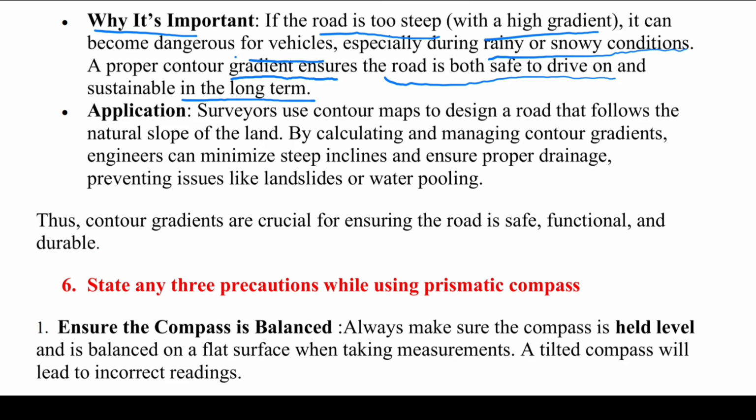And the application: if you are a surveyor constructing the contour map for roads, following the nature of the slope of the land, we need to know the slope of the land and how the terrain is. Based on that we have to fix the contour gradients, and we have to minimize the steepness.